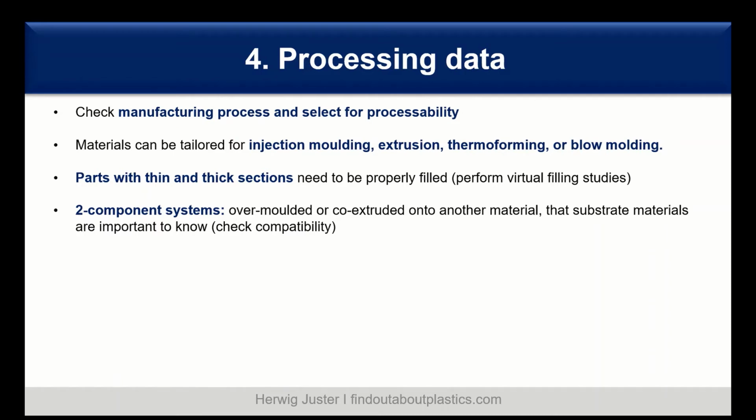Also have a look at the part design itself. It can be that there are thin or thick sections, so the selected material must be capable of properly filling these thin or thick sections. So it's good to also perform a virtual filling study, mold flow simulation, for example. But the best is to avoid such thick or extremely thin sections.